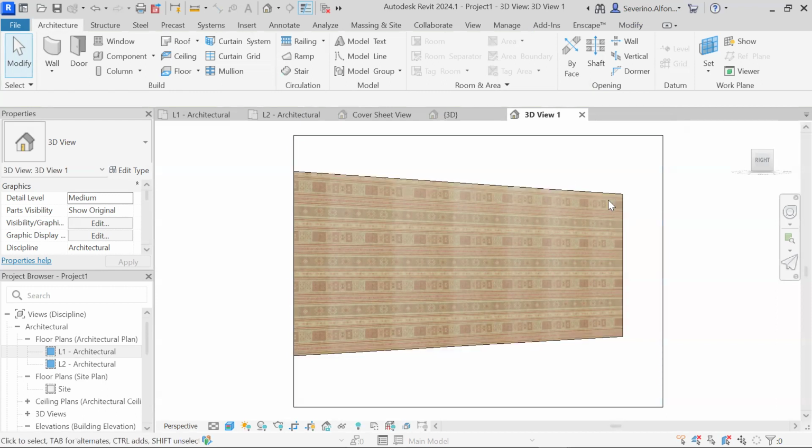We need to know where we can apply the material for that. So for partitions, it's straightforward. You need to know what layer you see and then change the material of that layer. Now for different things, different places, unfortunately. For stairs, you need to find the tread and the riser. Where do I assign the material? For light fixtures, you need to find where those are. And some of them are a bit more tricky than others. But all of the building components in the sense of walls, floors, ceilings, things that are not family oriented, they're all related to layers.